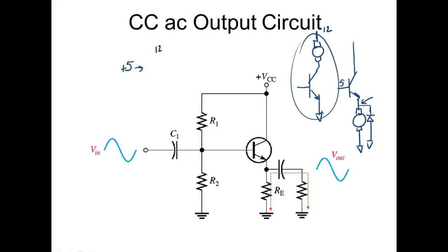For one thing, it's got a bunch of coils in there, right? Y'all understand that? If we take the power off the coil real quick, then that motor would induce a voltage back into my transistor and pop it, right? Also, when you turn this thing off, once something's in motion, it wants to do what? Stay in motion.